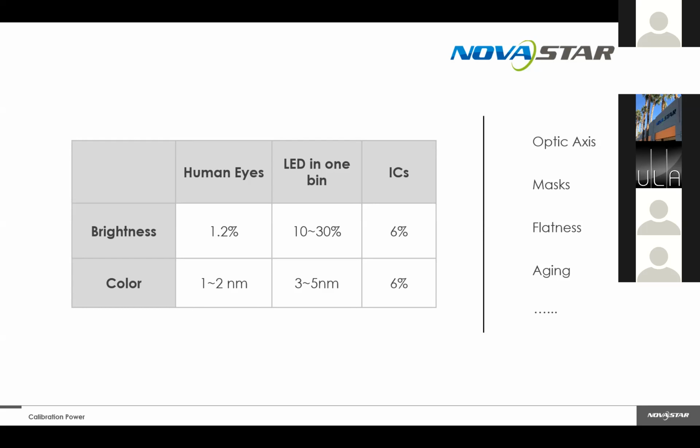The other thing you've got to factor, especially for your outdoor screens, is issues like masks that can get some UV damage. And masks also come from different batches as well. So they may look a slightly different tinge of grey in comparison to the one next to it. There's all sorts of issues that come down to batching. So if you're going to buy a screen, try and buy as much as you think you're going to need. And if you're going to buy another screen, then try not to run it side by side. It might be the same pitch, but you could potentially have color issues.